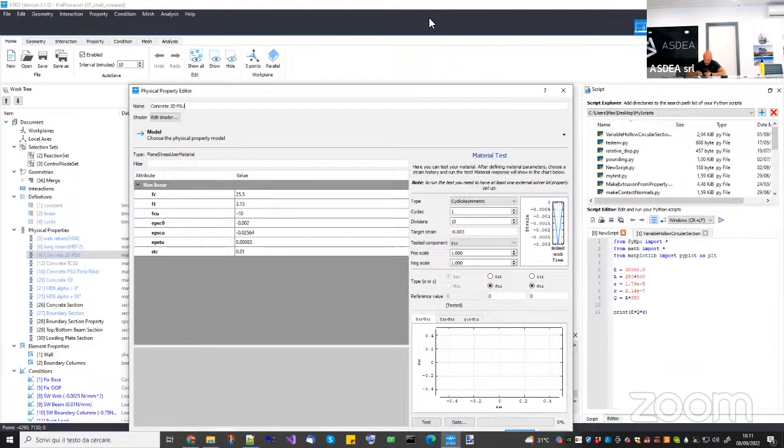If I do a drawing here, imagine you have a shell like this. Then at each Gauss point, you have many through-the-thickness integration points, okay? And in each integration point, you have a plane stress state of stress. So basically, you don't have out-of-plane shear. But for bending, it's fine enough, because even if you have only plane stress at each point, you can represent bending, of course.